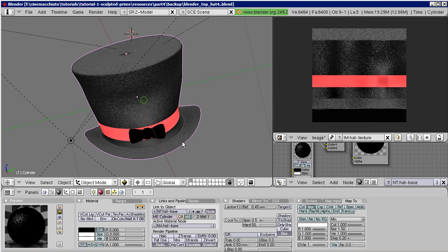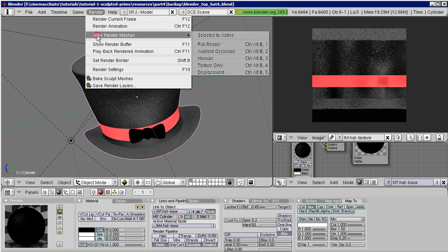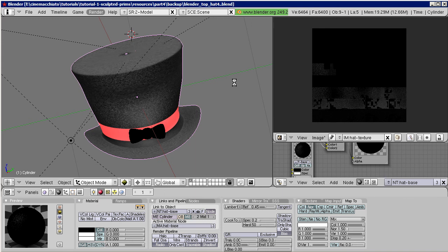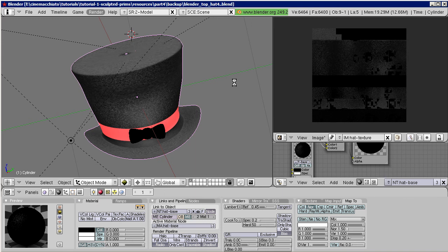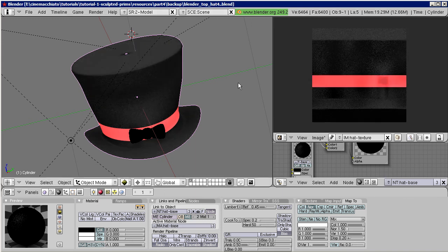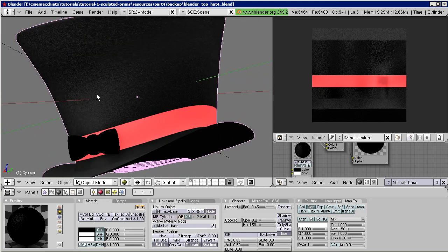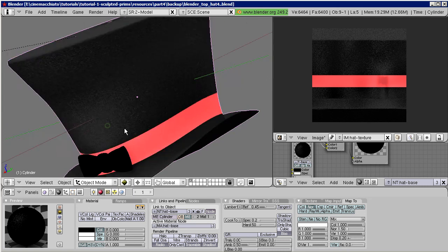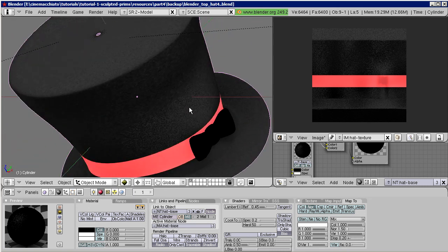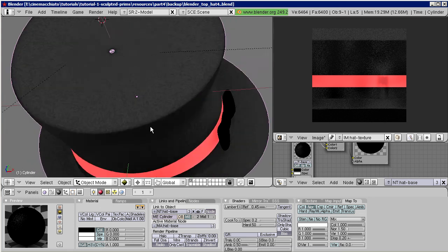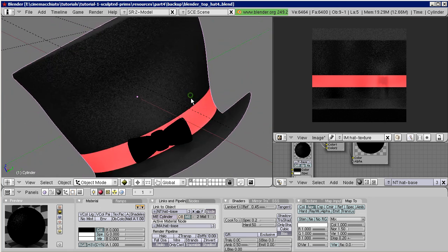Okay, try to reduce the specularity. Felt is not shiny. And bake again. So, by using a noise texture as normal map, we created a material resembling felt. We still can find improvements, and there may even be much better approaches. If you know an interesting approach, feel free to tell it to us.